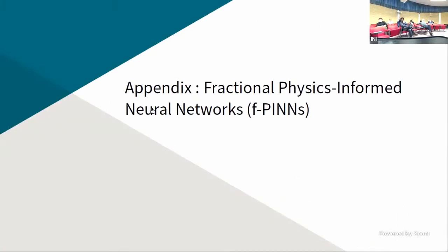Okay, so now that's a chicken and egg problem. For example, think. No, it's actually a chicken and egg problem. Okay, let's drop fractional, and let's just go to the traditional. So now you have an eddy diffusivity. You don't know what your eddy diffusivity value is. So you go on with your data, you compute it, and you find a nice fitting to that, and then you come back to your actual simulation. So now you know what the eddy diffusivity value is, and now you can simulate the flow that is under question.